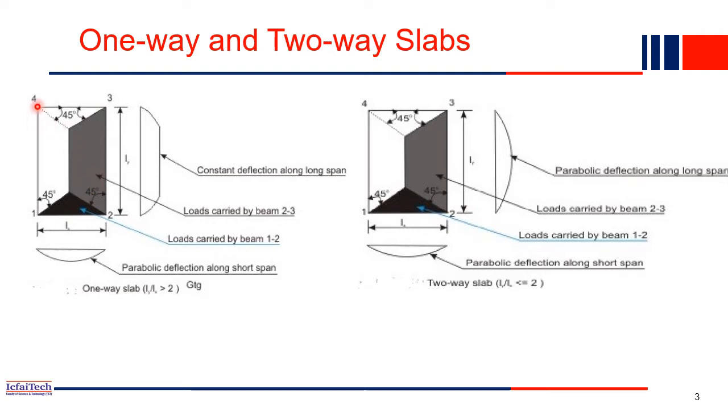So anyway, now you understand here, four columns are there, and on those four columns the slab is resting here. So now how will the loads be transferred to the beam? As I mentioned in the first slide also, loads are transferred from slab to the beam, then beam to the column, and column to the foundation, right? This is a typical load path of a structure.